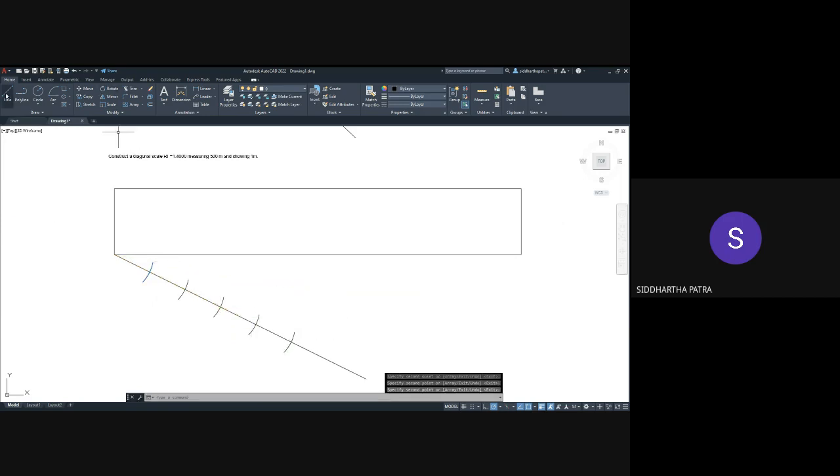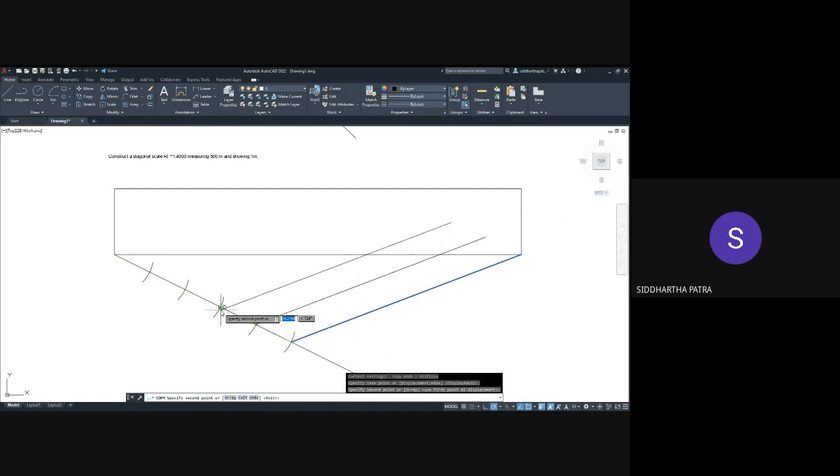And now I'll draw parallel lines, so I'm able to divide this line into 5 equal segments. Here I'm just copying in AutoCAD. In your case, you're supposed to draw parallel lines. If you align your drafter with the first line, then you can draw parallel lines from all the intersection points.